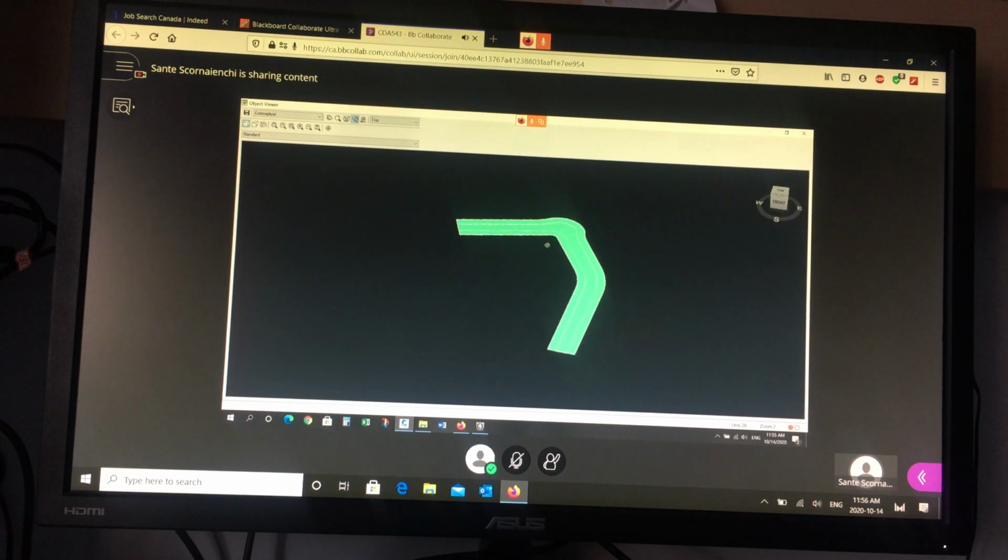So the crescent needs to be done as described. The cul-de-sac, the procedure is exactly the same. You need a horizontal alignment. You need a vertical alignment. You need a set assembly. And maybe you can use the same assembly here. Remember this assembly? 0 is here. It goes around, increases in this direction. Well, if you start here, right? If 0 is here and it increases in this direction, I can use the same assembly to go around the outside if the boulevard's on the left all the time.